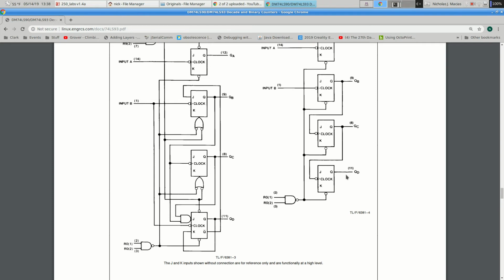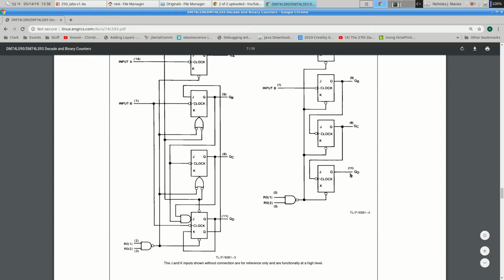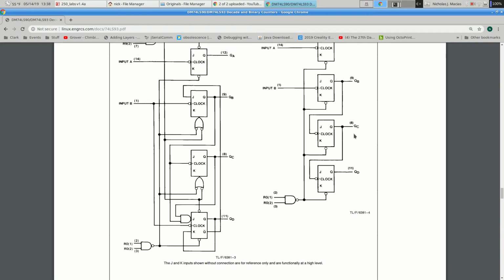So the timer you're going to test by itself already, right? So throw an LED on there. Keep the LED there. It lets you know that it's blinking. It makes you feel good. Something's happening. That's all good stuff. Connect the 555 to the input of the counter. And I would take 3 LEDs and hook them up right here. Put them side by side, put QB on the right, put QD on the left, put this one in the middle. And when you run your circuit, you should see those 3 LEDs counting in binary.